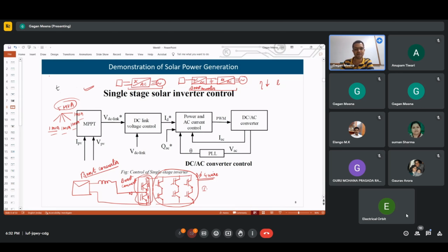Whatever control theory we have studied with PI, the inputs were always DC, not sinusoids. PI is very simple, cheaper, and also robust, so we want to use PI, but we want to avoid this cumbersome design. We want a simple controller.